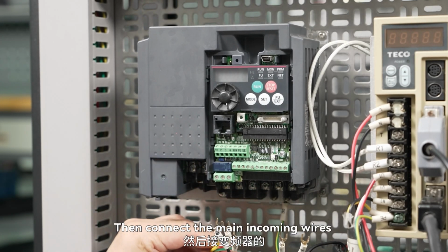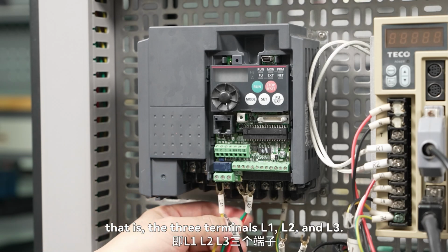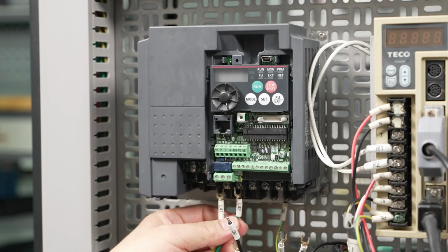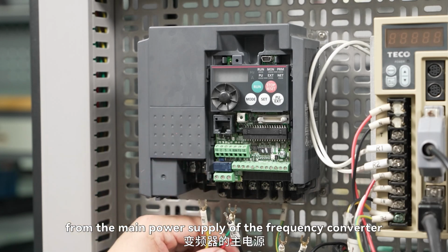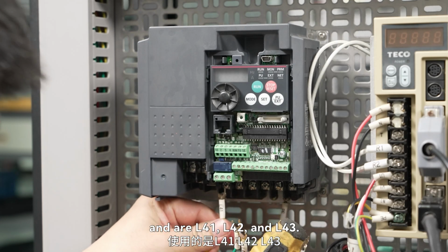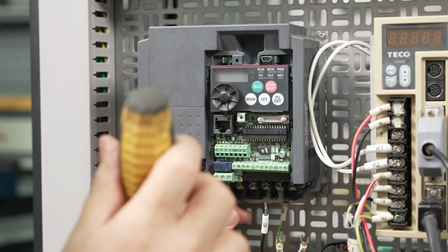Then connect the main incoming wires of the frequency converter, that is, the 3 terminals L1, L2, and L3. These 3 wires come from the main power supply of the frequency converter and are L41, L42, and L43.